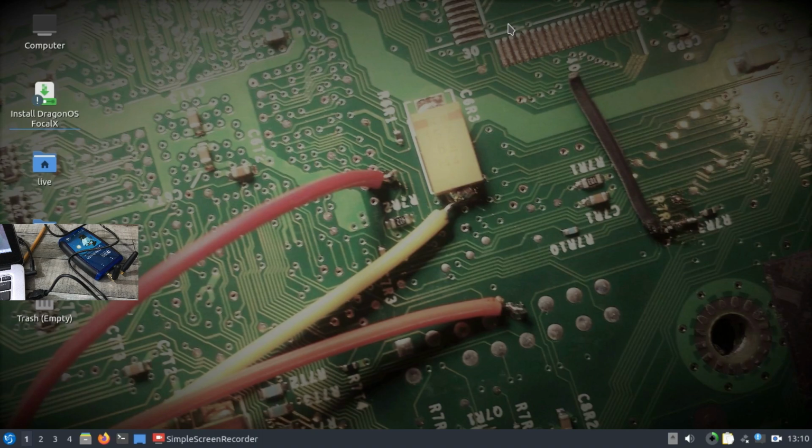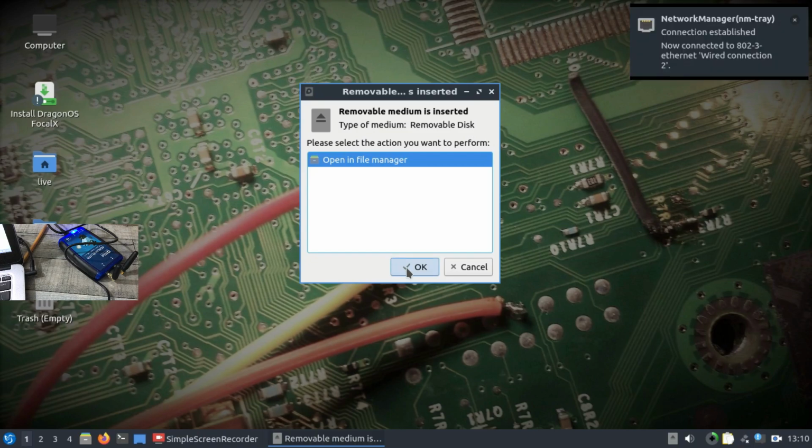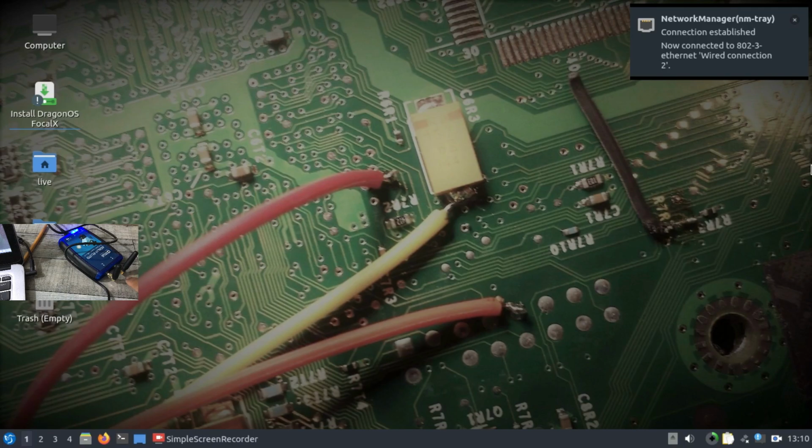We're going to look at a tool called QRadiolink, and we're going to explore that tool. So for that reason, I'm going to connect my Pluto-SDR. And the reason I'm using Pluto-SDR is because Pluto-SDR is a full duplex device, and I'm going to use the full capability of Pluto-SDR to transmit from one end, and we're going to try to receive it on the other end. So I'm going to try to transmit a signal from here and try to receive the signal on the receiving end.